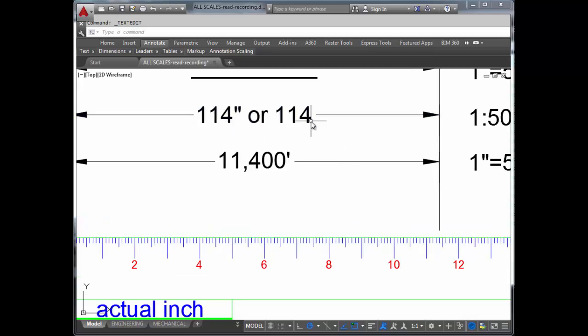With this answer, it's correct to either put inches or nothing, depending on how the drawing is set up. If the drawing indicates that it's in imperial units or metric, right in the title block, we may not need to put that unit of measurement. If it's not as clear, it might be easier to put that unit of measurement following the value. So it's the choice of the drafter.